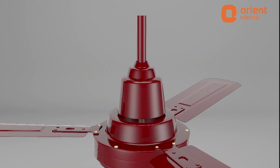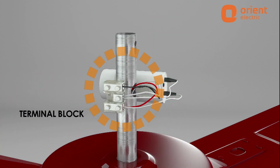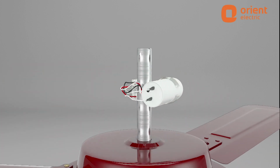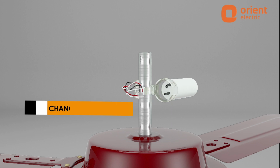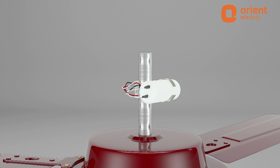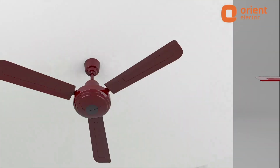You should also check for connections at the terminal block of the fan and change them in case they are incorrect. A defective capacitor could also make your fan stop working. In such a case, simply change the capacitor. In case of open circuit in the regulator, check the connections and set them right if not connected properly.